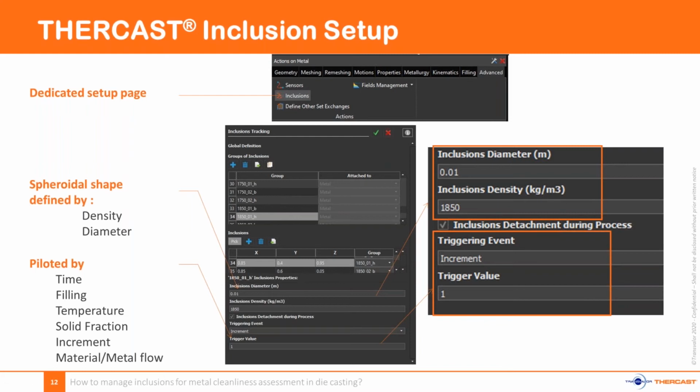If I would have used a millimeter, sorry, megapascal SI template, the diameter should have been entered in millimeters, and this would have been millimeter in the brackets, whereas the density remains in kilogram per cubic meter because it is SI in both unit systems, millimeter MPa SI or meter Pa SI. So in case of non-SI units like the British units, it's inch and BTU.